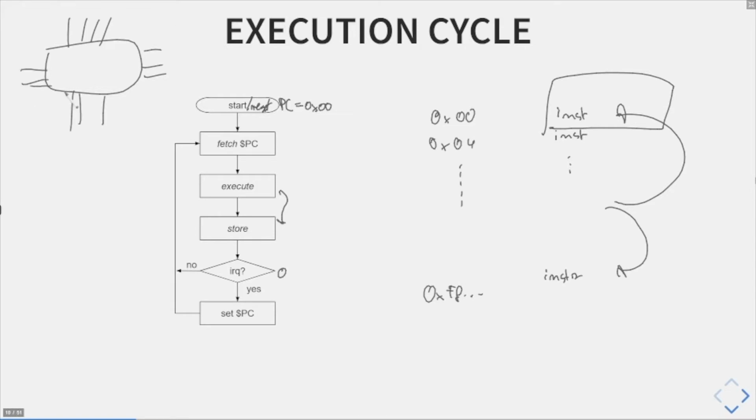What you can have here is special designated interrupt lines, where there's a comparator behind this, which is compared, for example, to VCC. What you can then check for is whether this line is high or low. And if it is, you stop your normal execution cycle.